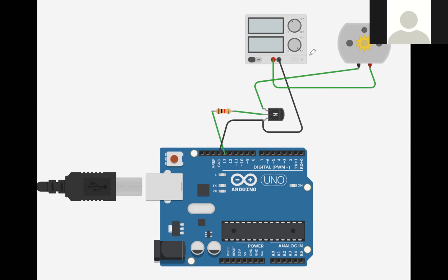So what we do is get a 12-volt power supply or a 12-volt battery, and we use the transistor here as a switch. Sometimes you'll hear it referred to as a relay, because a relay is basically that: a switch where a very weak input signal is allowed to control a very strong output signal.